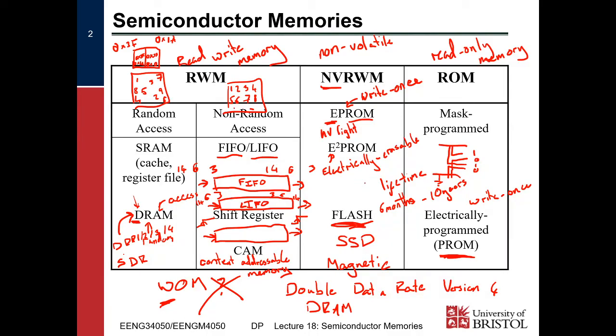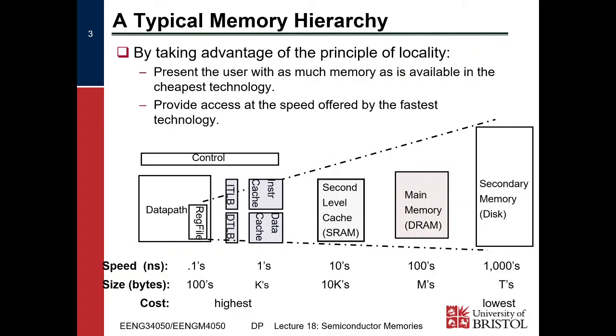So we've got all these different styles of RAM, of memory. We're focusing on SRAM and DRAM, right? So now we're going to look at something called the memory hierarchy. Basically, a fast memory is very, very expensive, right? So this is your sort of flip-flops and your SRAM over here. Right, flip-flops are actually more expensive than SRAM.